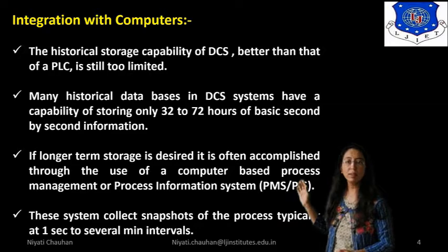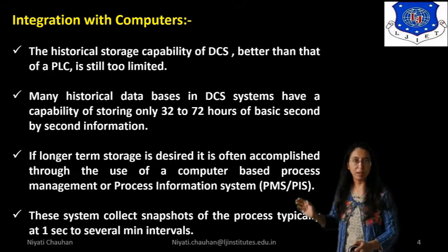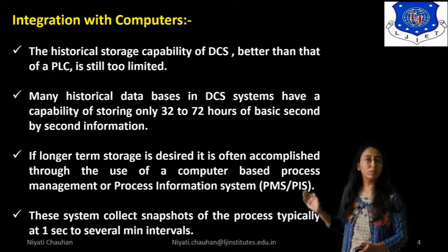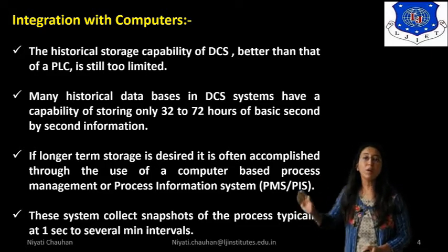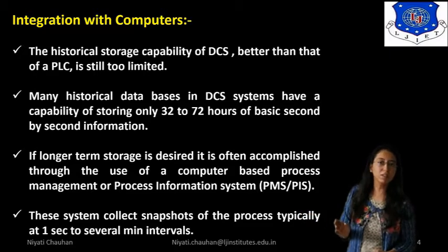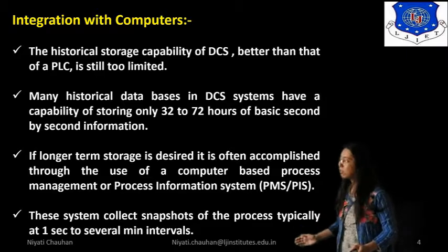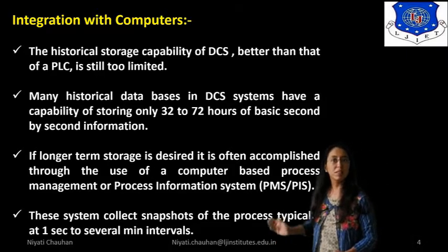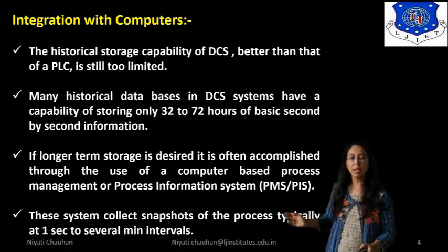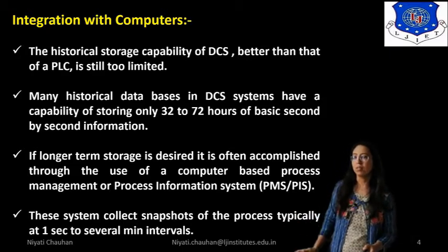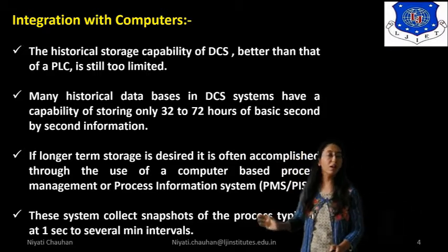If longer term storage is desired, it is often accomplished through the use of a computer-based process management or process information system, PMS and PIS. This system collects snapshots of the process typically at 1 second to several minute intervals. So in this topic we have discussed integration with computers.